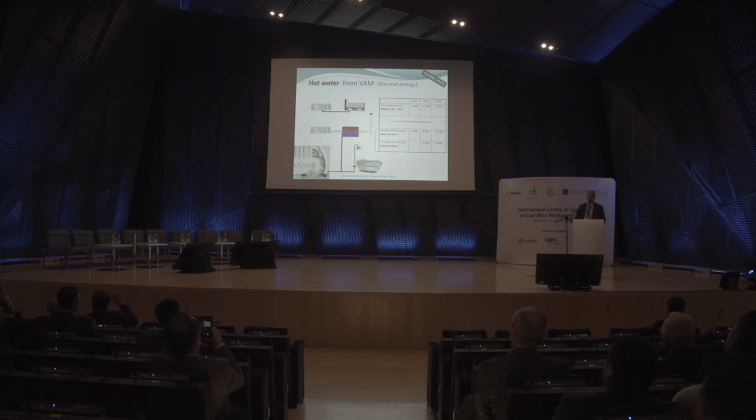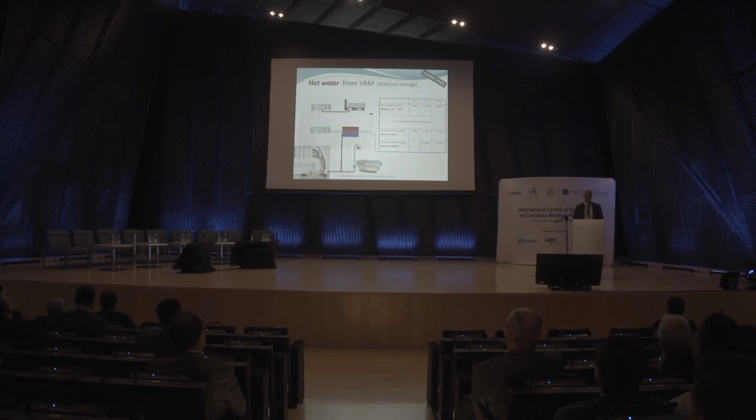So depending again on concentration, 0.3%, 3 megawatts; 0.9%, 18 megawatts, and this is if you get the heat straight from the bed. The difficulty is to find a very large consumer of energy close to the mine shaft. Normally it's enough to have a secondary heat exchanger on the exhaust, and then you can still get a lot of energy out, which is normally quite sufficient. Then you can make electricity. There you have numbers for that.